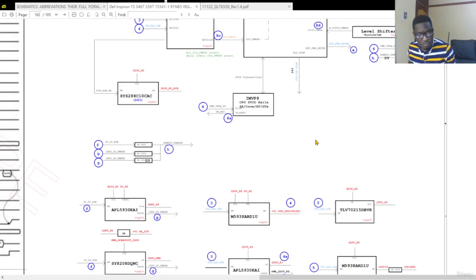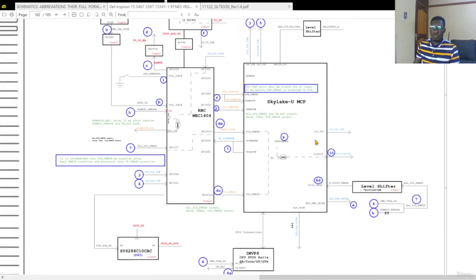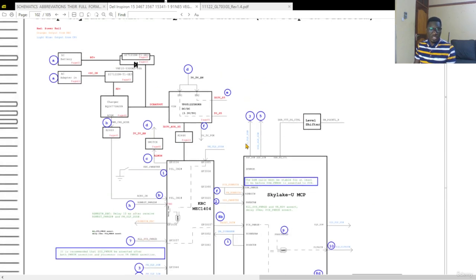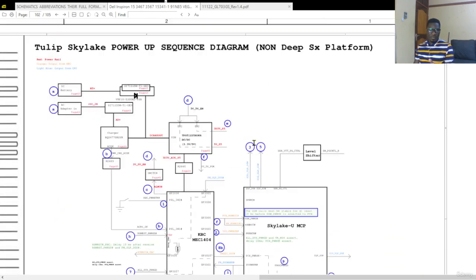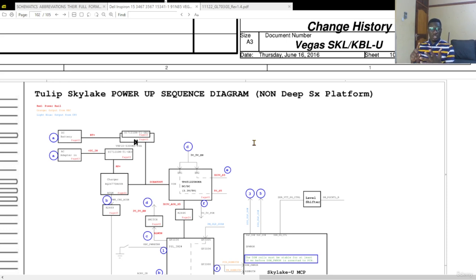If you're facing a laptop which is not turning on, turns on and then doesn't return post, turns on and then goes off, turns on and gives some kind of errors, or does not turn on at all, this is the step-by-step. It's found in the schematics and shows you how to follow up and trace the motherboard. So not every schematic has this diagram the way you see it here. Commonly I found it in ASUS, Acer and some Dell. Few HP have got it and Lenovos usually don't have.